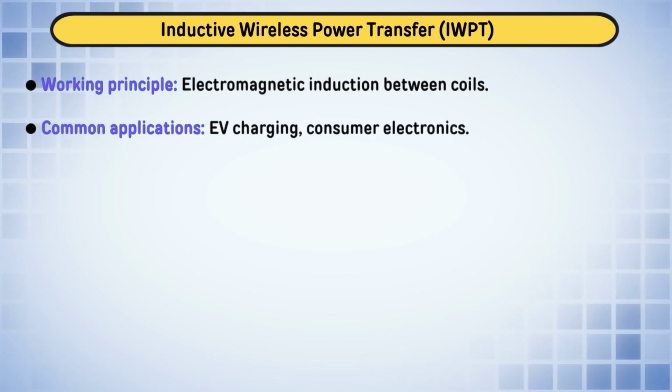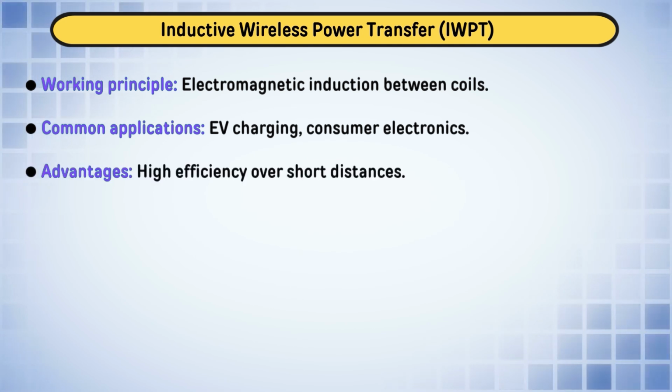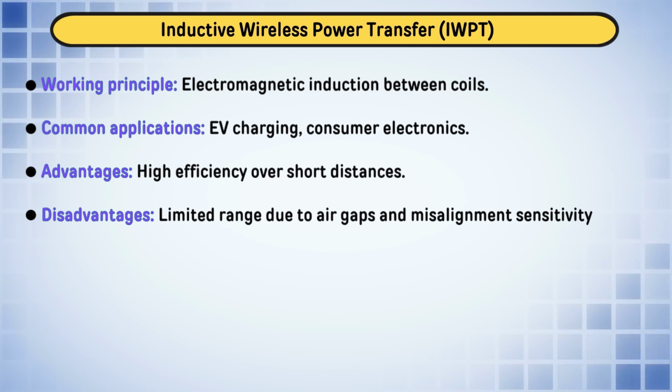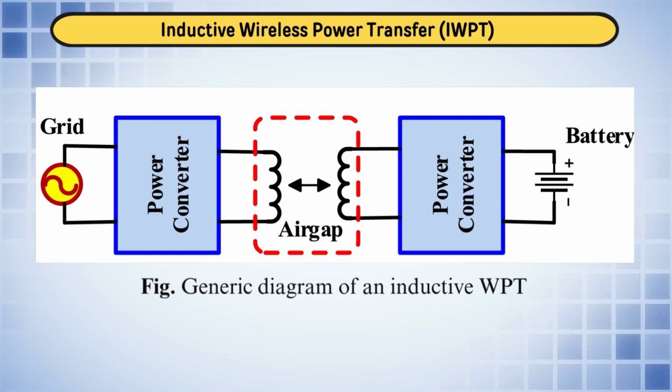Here the switch is in series with the supply. However, in the boost converter the switch is in parallel with the supply and the inductor is in series, and then we have the boost converter. Now, if we move to the buck boost converter, the switch is in series with the input and then one inductor and the diode is connected, and in all three units we have a capacitor which is utilized to mitigate the ripple in the voltage.